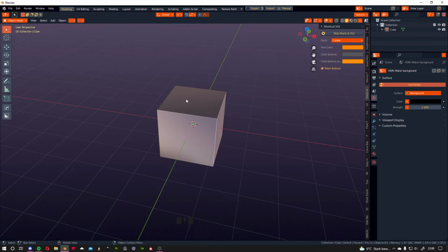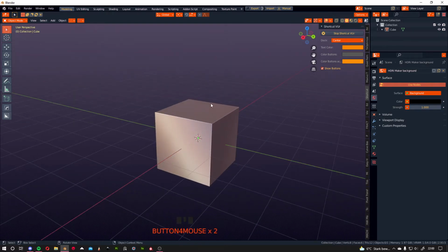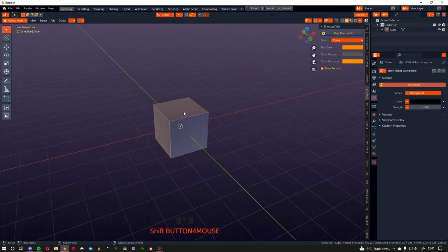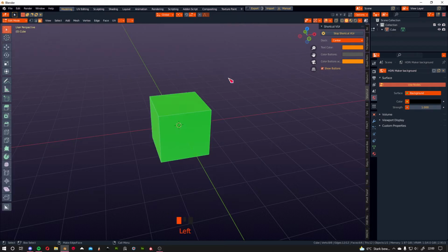Standard modeling, what does it mean? When you have a cube, it has 6 faces, 8 vertices, and a dozen edges. Everything can be edited when we go to edit mode. So how can we do this? The first thing is pressing the Tab button, then you come into edit mode, or you can choose edit mode up here.